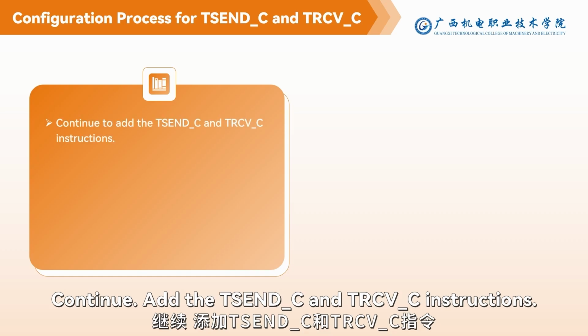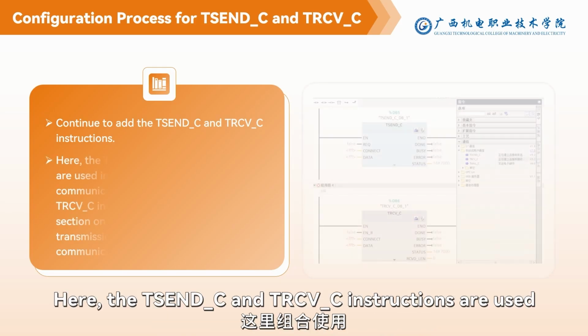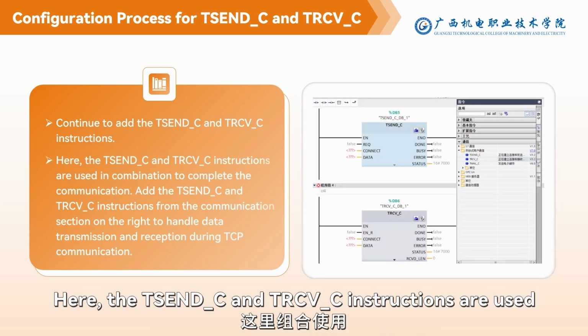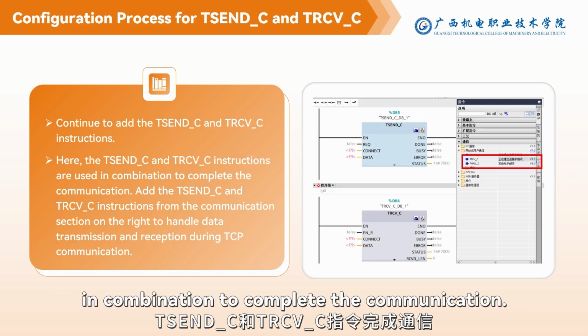Continue. Add the TSEND and TRCV instructions. Here, the TSEND and TRCV instructions are used in combination to complete the communication.